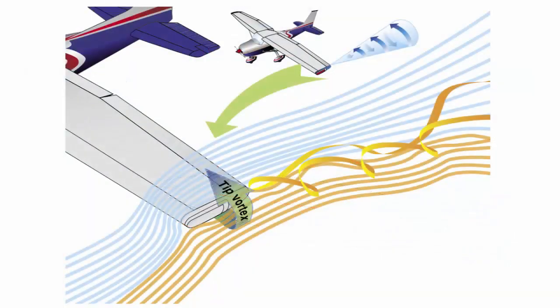So far, we have only focused on the airflow across the upper and lower surfaces of an airfoil. While most of the lift is produced by these two dimensions, a third dimension, the tip of the wing, also has an aerodynamic effect. The high-pressure area on the bottom of an airfoil pushes around the tip to the low-pressure area on the top. This action creates a rotating flow called a wingtip vortex. That vortex flows behind the airfoil, creating a downwash that extends back to the trailing edge of the airfoil. This downwash results in an overall reduction in lift for the affected portion of the wing.